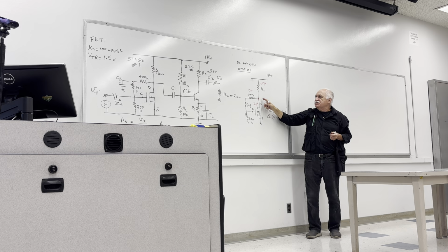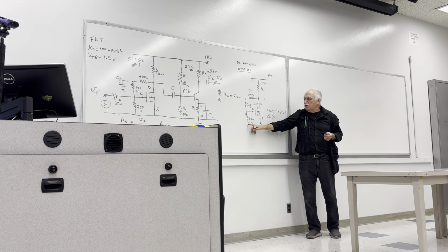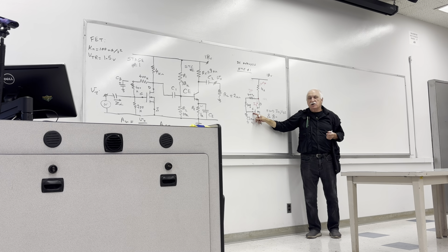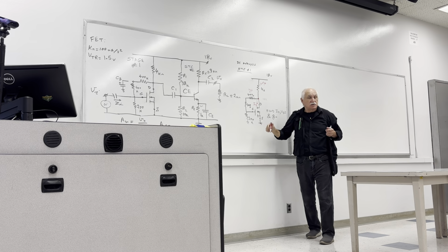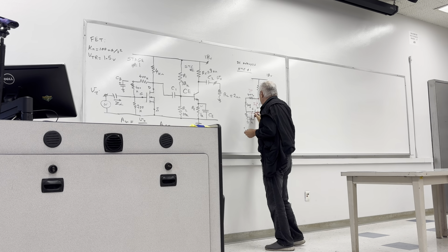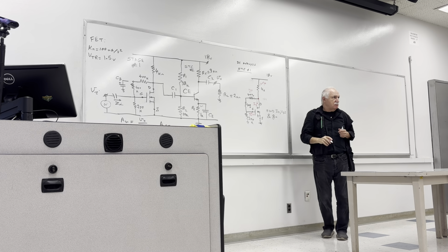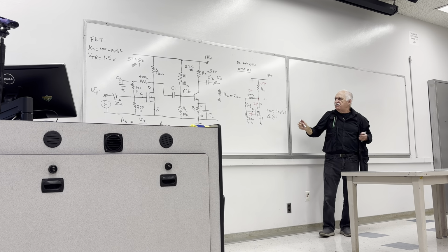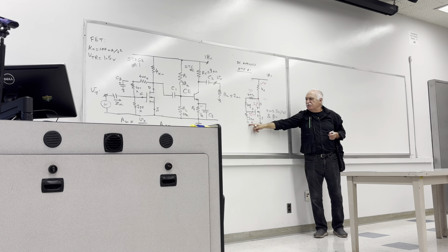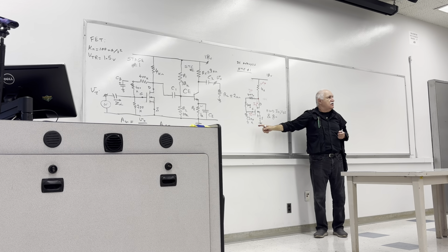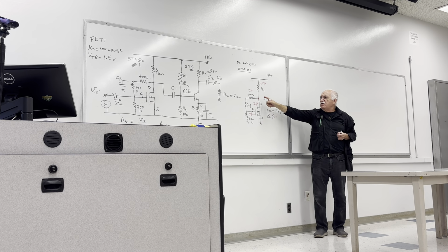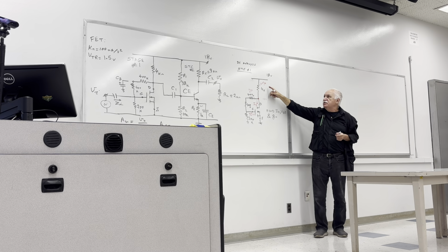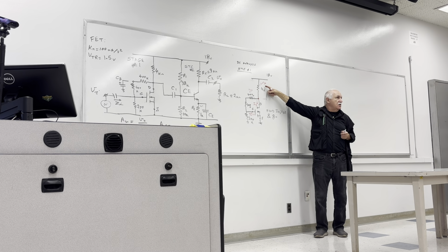But if I take that voltage, 10 volt, minus the node voltage in here, of course, recall that IG is 0 in the FET. DC IG is unconditionally 0 in an FET. So this 10 minus voltage over there divided by 400 is going to be a very, very small current in comparison to the 2000 microamp.